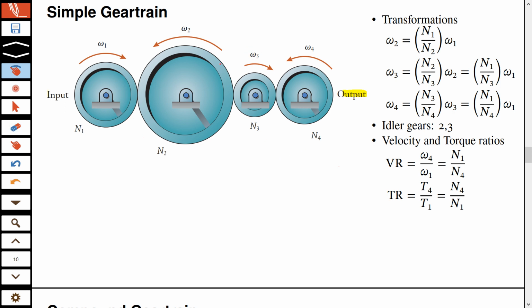So similarly, these two are now opposite. So if this is going upward, this also has to go upward, which means that this has to be clockwise. And again, these two, this has to come downward, this has to come downward. These angular speeds are opposite. So it's very easy. Now, I expect you to know this sense. You should be able to indicate proper directions.